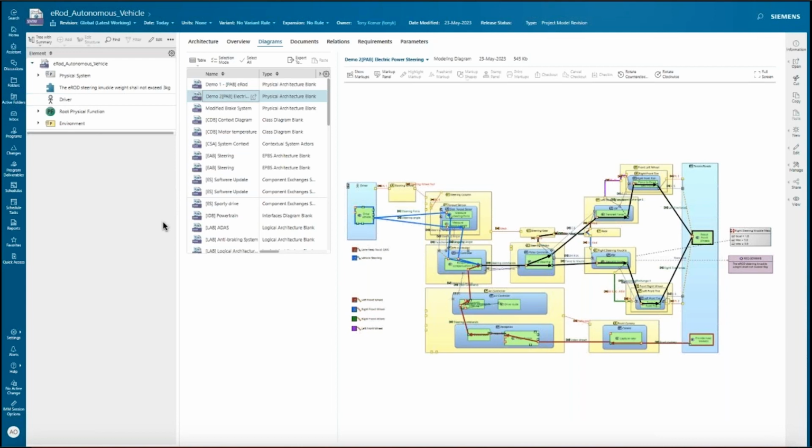And if you're familiar with COSI, they talk about RFLP, right? That requirements, functional, logical, physical structure. We create a conceptual bill of material for that we can align to the engineering bill of material. All of that information is available to everyone inside of Teamcenter without needing access to system modeling workbench in this case, but same way with all the other tools that we integrate with.